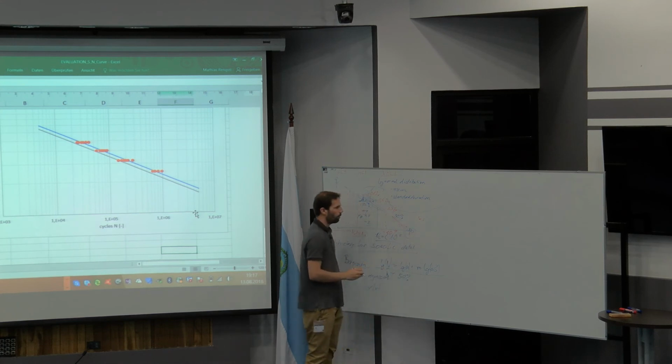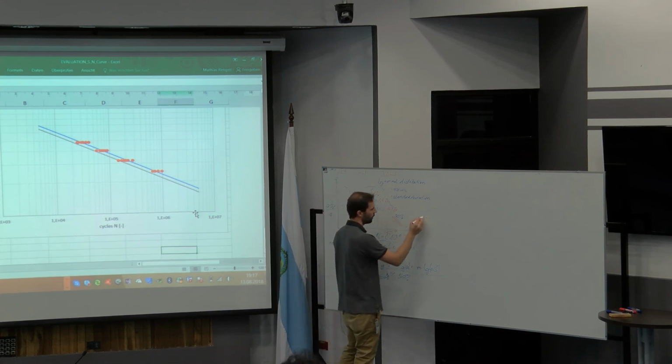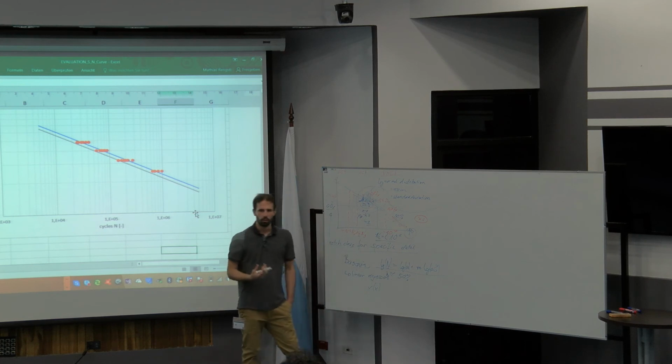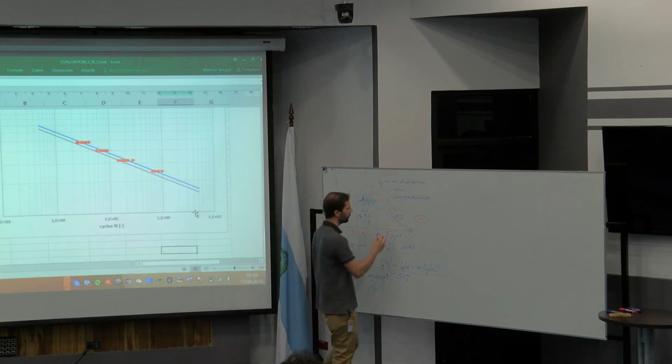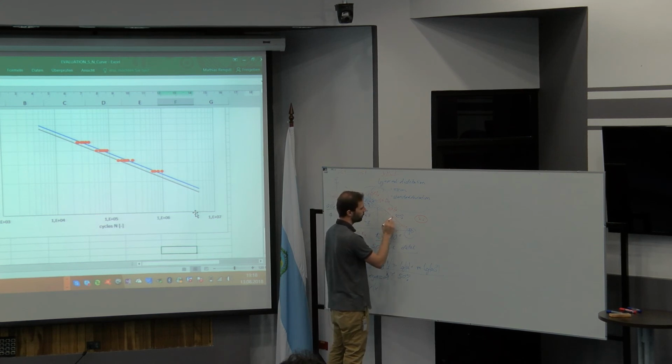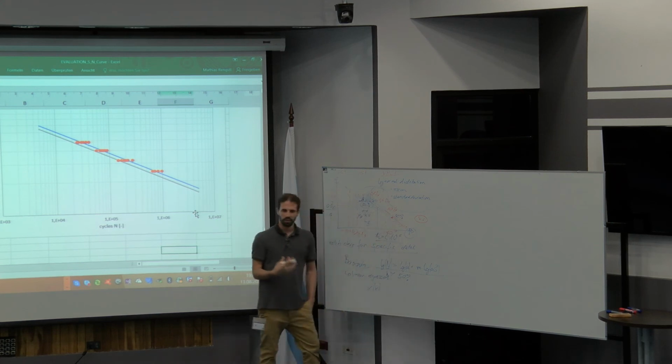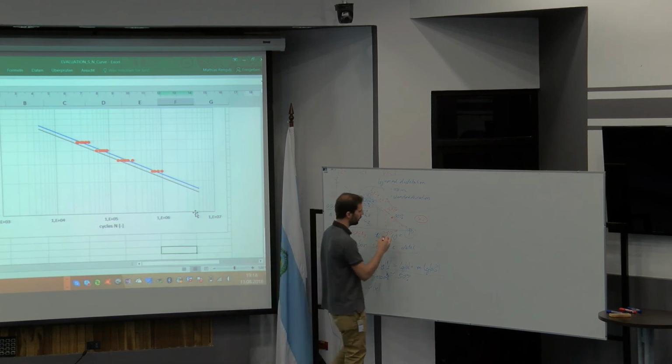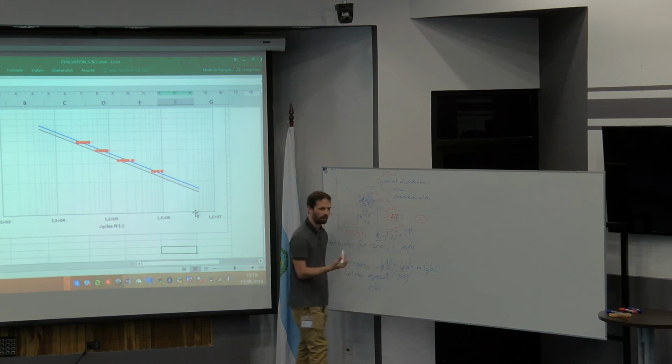So what you have to do if you want to look at the durability of the fatigue strength, you go there, you test here, and if the material or the specimen doesn't fail at the level of 10 over 7, you increase again the tested stress range. And so at the end, by increasing and decreasing, you get here some specific values.